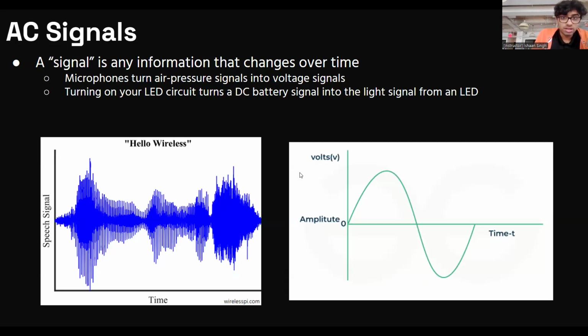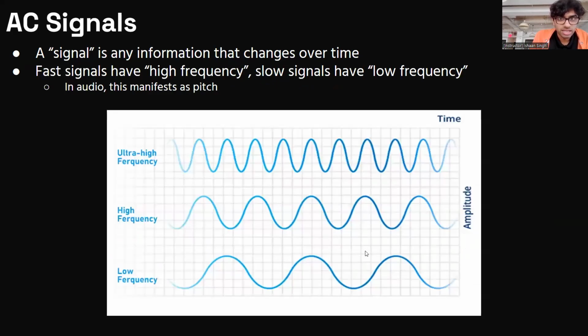So everything is a signal, and all of these complicated looking shapes of signals can be decomposed into pretty shapes like what we have on the right. That's the goal of signal analysis. We're trying to decompose a signal and think about them purely as frequencies. And these shapes, these sine waves, we can think about at their frequency range. So we have some signals that are low frequency, some signals that are high frequency, and so on.